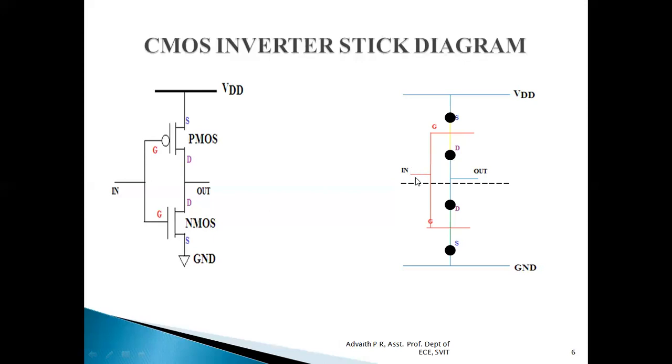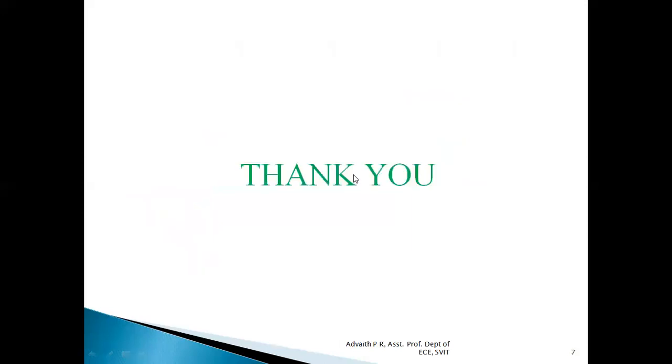But normally for gate inputs, we stop at this polysilicon. We normally will not connect metal. Even if we connect metal, it is not wrong. I hope that you have understood the stick diagram representation of inverter.